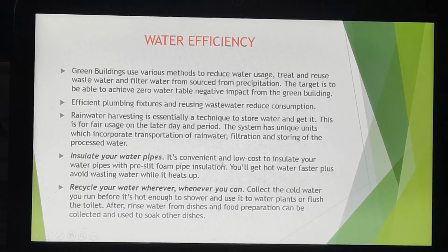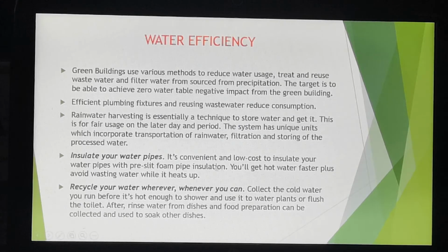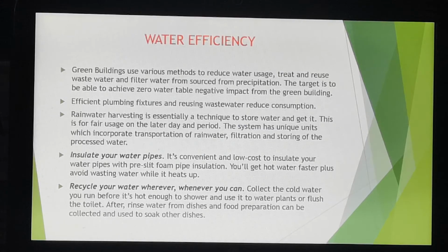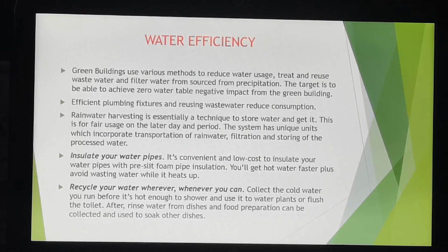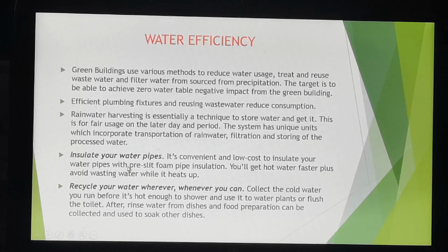So it can be convenient and low cost to insulate your water pipe with the pre-slip foam pipe insulation. So what you can get is your hot water faster, plus avoid wasting water while it heats up. So you don't waste energy, electric current or anything, just to get your water hot, because if you insulate your water pipe, the process to heat up the water is faster and saves more energy.